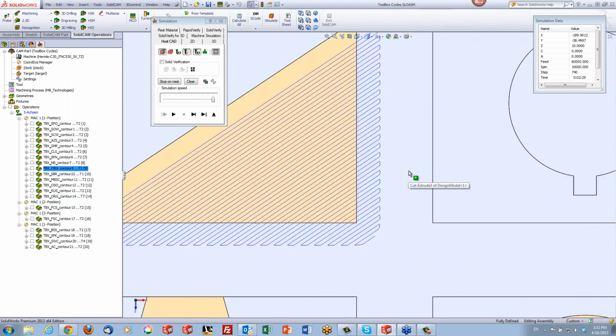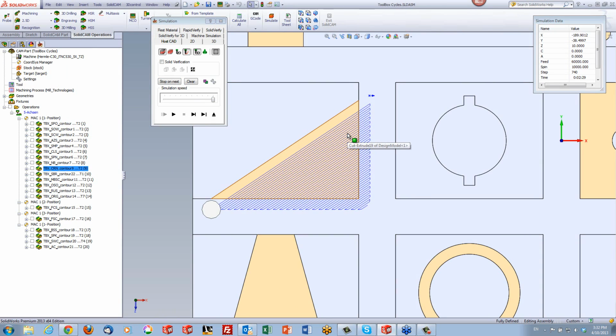What you see actually happening is that in the clear offset on a profile, if you pick this line, it'll go all the way out over here. This line over here will actually have a geometry up until this area. The toolpath will be up until this area over here. This automatically cuts down the excess area, and it only works in that corner. It'll automatically create a corner going horizontally this way and vertically this way until they meet, and that will be your corner to be cut. This is specifically made for straight corners as shown over here. Now,